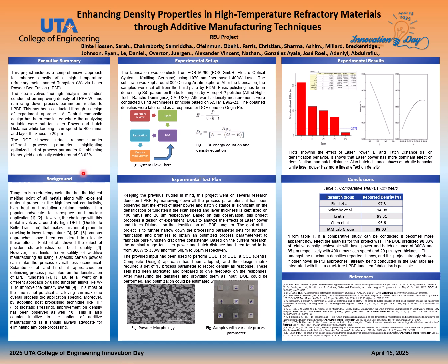Now let me discuss more about the background of this project. Why tungsten? Because tungsten in additive manufacturing is a challenging material. Why? Because it has a high melting point and a high DBTT, and this causes tungsten, when it goes through solidifying, reheating, and remelting in laser powder bed fusion, to have a tendency toward cracking, and these cracks and micro cracks decrease the density of the bulk sample overall.